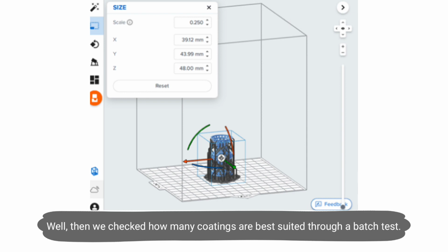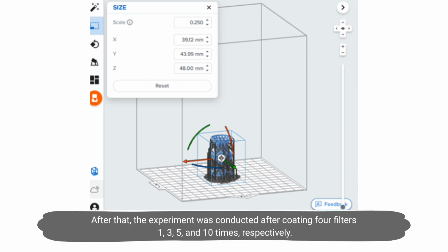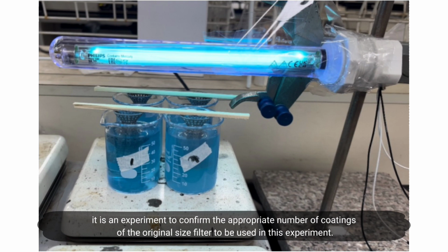Well, then we checked how many coatings are best suited through a batch test. We made 4 filters for batches that are 25% size of the original filter. After that, the experiment was conducted after coating for filters 1, 3, 5, and 10 times respectively. By comparing the treatment capacity of 1 ppm methylene blue solution, it is an experiment to confirm the appropriate number of coatings of the original size filter to be used in this experiment.